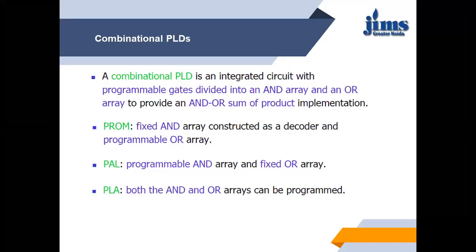And the last one we have PLA, programmable logic array. Both AND and OR arrays are programmable. So these are the major differences. In PROM, AND array is fixed. In PAL, OR array is fixed. And in PLA, both arrays are programmable.